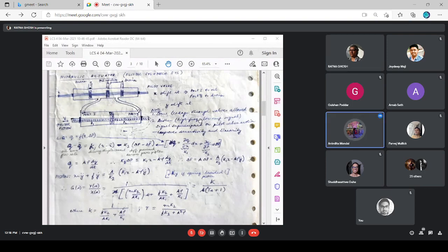I'm in the neutral position, when the gear is. So what happens is that the engine is still running, right? Since the engine is running, the motion of that engine itself creates a high frequency signal, and it's a very low amplitude, right? You don't jump on your seats because of the engine being on, do you? No, ma'am. But there's a constant movement there, right? Yes, ma'am. That is nothing but a dither signal.